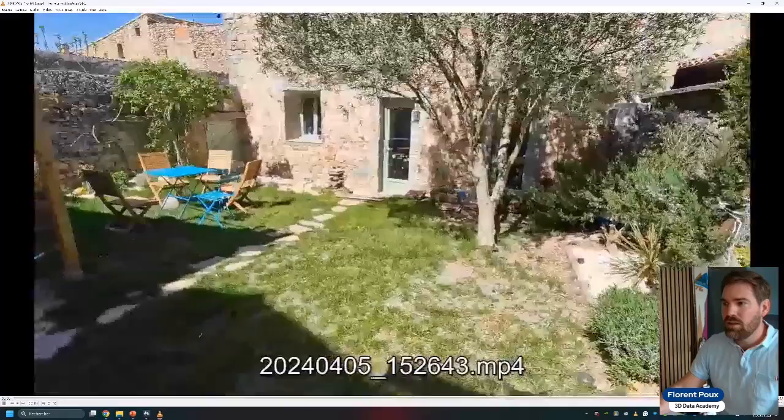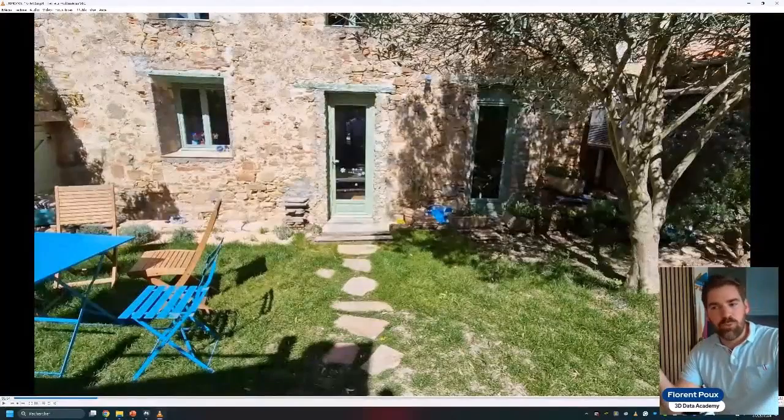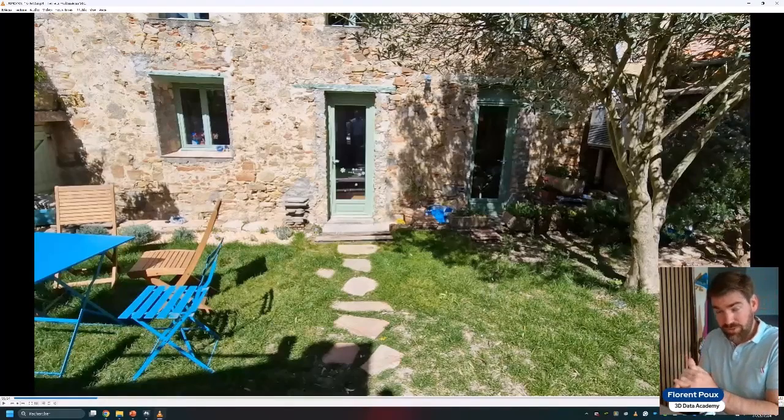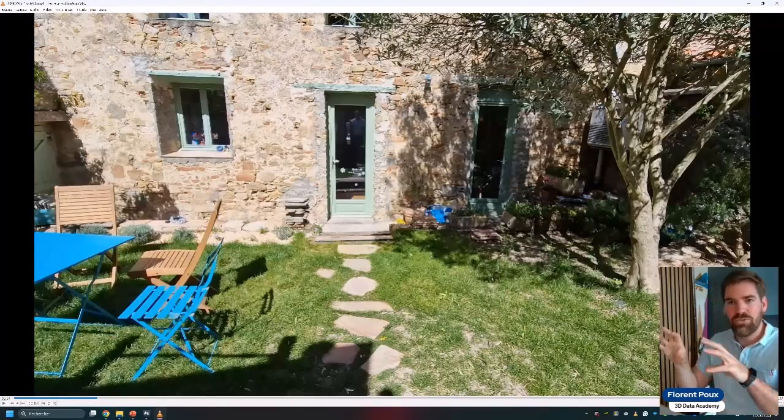A garden. Yeah, this is the kind of video that you can shoot. There are some principles that are the same as photogrammetric principles. Any points that you want to have reconstructed need to be seen from at least 2 images. When you shoot a video, what PostShot will do, or what you need to do, is to sample your video and extract frames at any speed you want, like 1 frame every second or 5 frames every second. And then with PostShot, you have the ability to let it decide, based on quality, if it detects some blurry effects or things like this, which frame it will use.